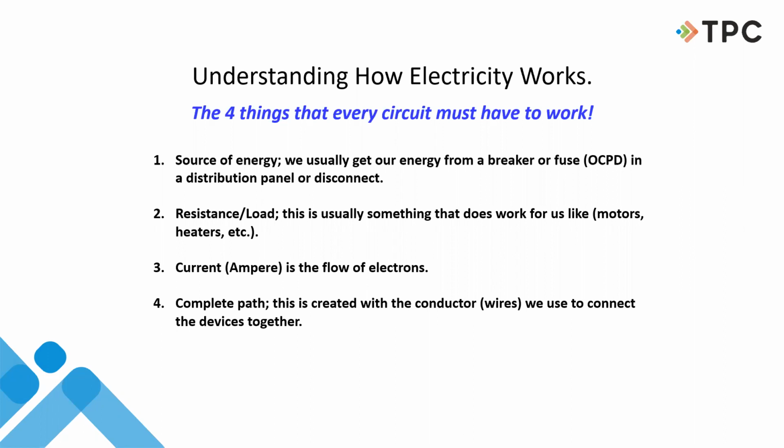And those are very important things to know, because if we're troubleshooting and I'm using an electrical meter, number one, I need to know to get it on the right setting. And number two, if I'm checking something, I really need to know what the voltage is supposed to be, not just accept something that my meter tells me.